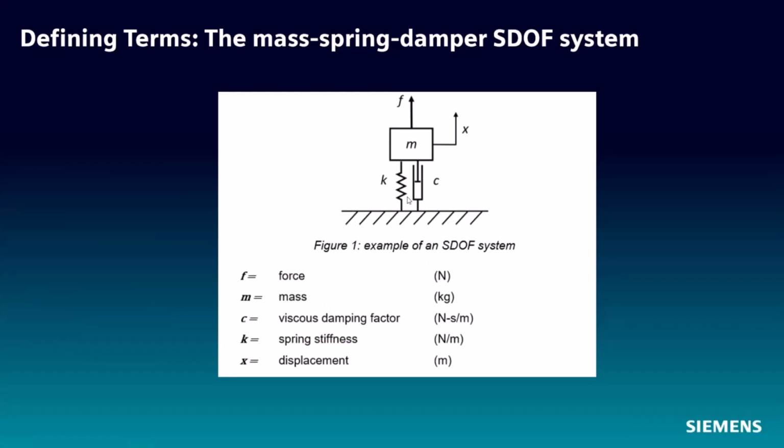We talk about damping of complex structures, but we're always bringing that damping back to SDOF systems, single degree of freedom systems. A single degree of freedom system has a mass, a spring, and a damper. Sometimes there's base excitation, sometimes we're dealing with free vibration, where you have maybe an impulse that gets your system moving. And what we have is a force, because this mass is moving. There's some acceleration as the mass moves up and down, changes in acceleration as we saw in the previous slide. And so we have a force that's occurring here, right?